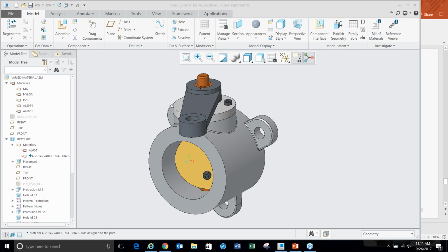Remember when you're mirroring an assembly, there was an option to make it geometry dependent, and there's also an option to make it placement dependent. Let's say, I'm just envisioning your question like this, you had a flange with a bolt hole pattern, and that is a subassembly. And you change the bolt hole pattern, for example, from 9 holes to whatever. So the placement is updating, the bolts update. So if on the mirrored subassembly, if you were to reuse it, it will also update, provided you had selected the dependent placement option.